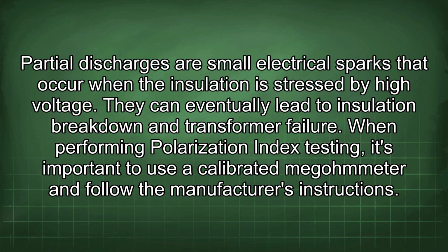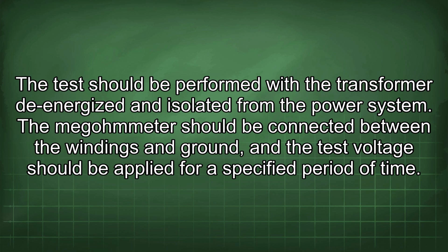When performing polarization index testing, it's important to use a calibrated megohmmeter and follow the manufacturer's instructions. The test should be performed with the transformer de-energized and isolated from the power system.